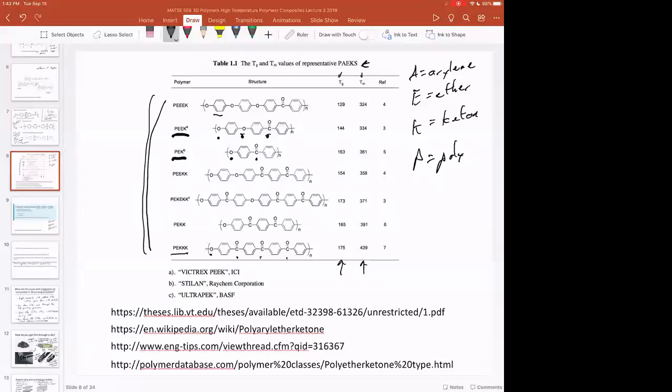Sometimes it's left unsaid. Sometimes, if you get a funny polymer, there will be some misinformation. So people like to say that PVC is semicrystalline, and it's not. There is no Tm for PVC in the polymer handbook, and so you need to look at some of these materials with a critical eye.